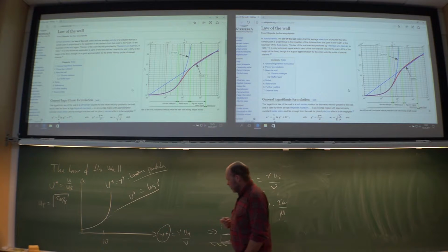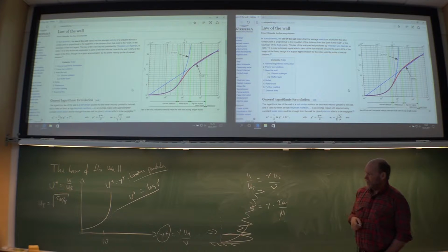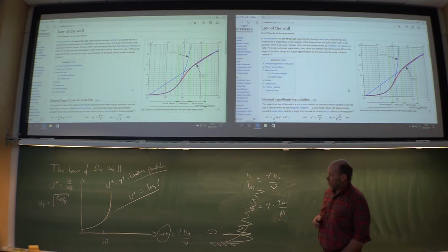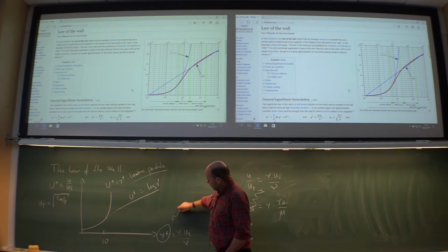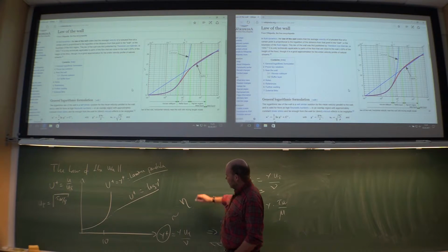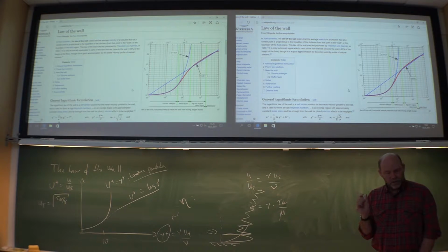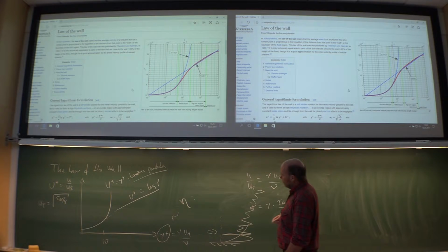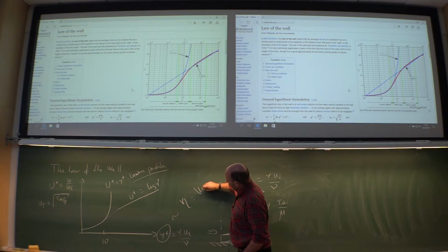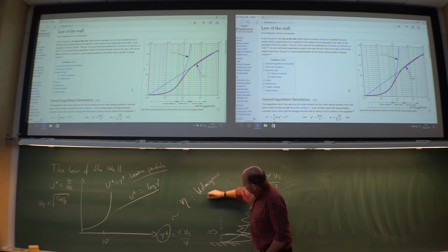This plus unit in distance, okay, you have to insert numbers to find how many meters we are talking, or actually millimeters typically. You can also say that this will roughly equal what is called eta, which is the length scale of the smallest turbulent motion. It's called the Kolmogorov microscale.